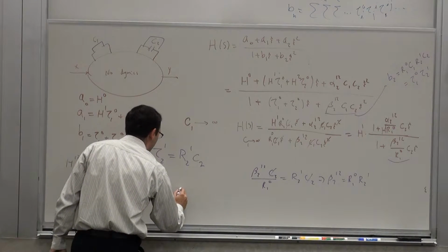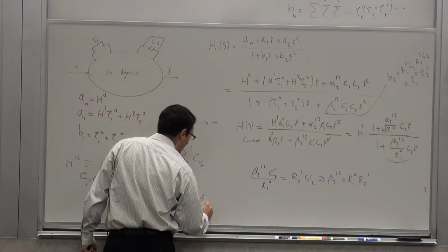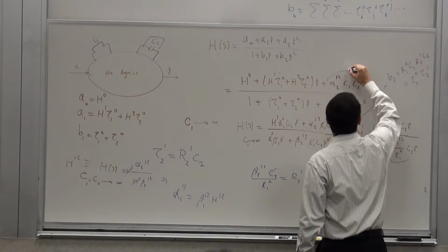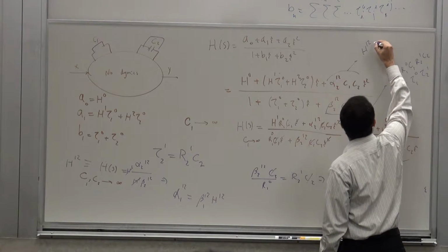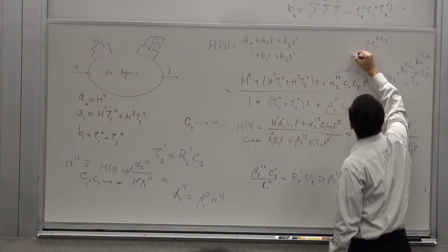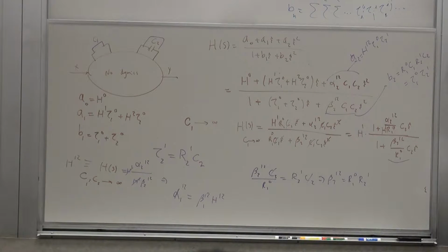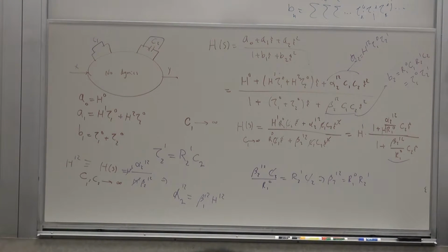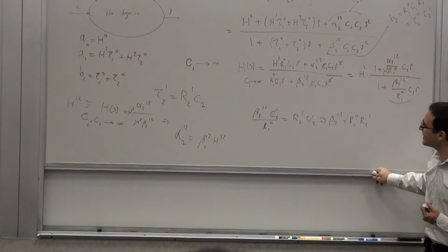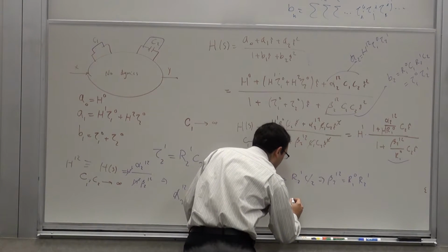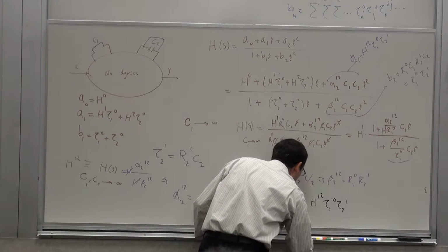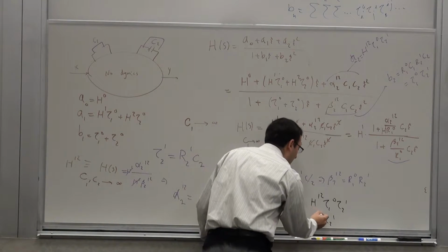So basically, alpha 2, 1, 2 is simply beta 1, 2 that we just calculated times H12. So it would be the same thing. This term would be exactly the same, except for the fact that it would be H12 times tau 10, tau 21, which is A2. That is alpha 2, 1, 2. Yes, alpha 2, 1, 2, yes, thank you. It's an intermediate variable, it doesn't matter, but yes, that's correct. So, this basically shows the special case of a second order system. So to summarize, this was the derivation. But to summarize, what that tells you is that in a second order system, A2 is simply H12, tau 10, tau 21, and B2 is tau 10, tau 21. You don't need to remember the derivation, but the result.